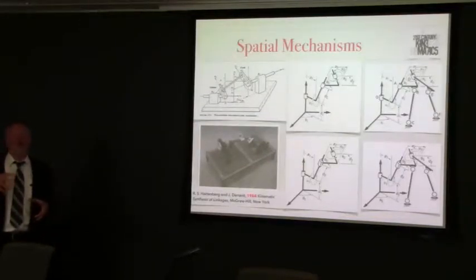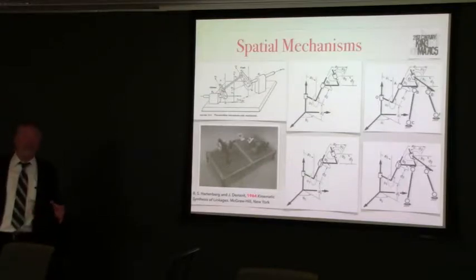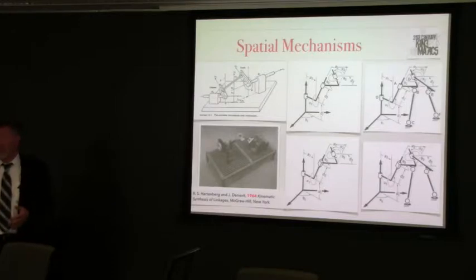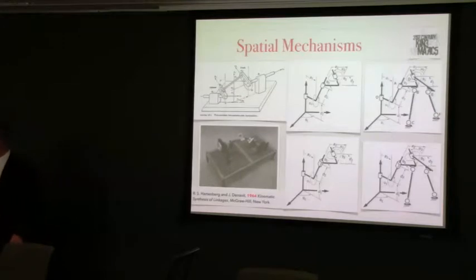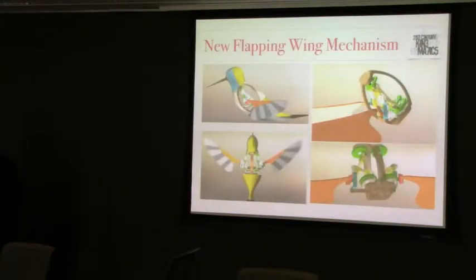The decision to work on a purely open chain with 6 degrees of freedom rather than 1 degree of freedom turned out to be an enormous simplification of the problem. It was a great step forward. We could actually work in 3 dimensions using control theory combined with kinematic synthesis and analysis. But we did have to pay the penalty that we had to work with higher degree systems.